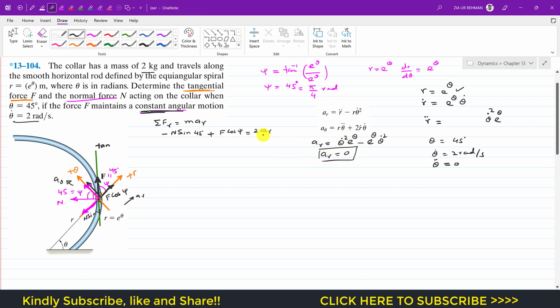Now if I put AR equals 0 in this equation, this side will be equal to 0, and psi is also 45. If I divide the whole equation by sine of 45, sine of 45 and cos of 45 have the same value, so we can write minus n plus f is equal to 0, or f is equal to the normal force.